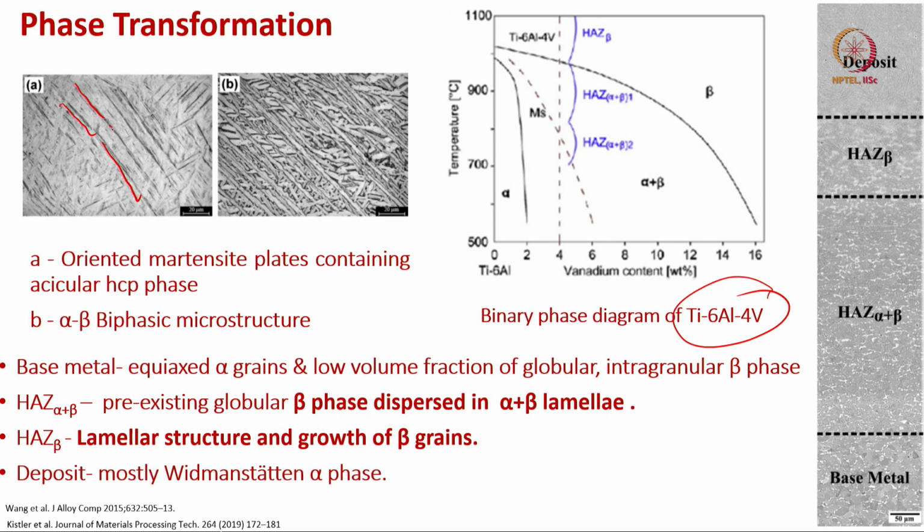Those who are from a metallurgical engineering background know that martensite is one of the metastable phases, and martensite in steel essentially results in high hardness of the material. Martensite is named after Martens, a German scientist. This is alpha, beta. These are biphasic microstructures, and these different phases, as you see, also appear with different morphologies in these biphasic microstructures.